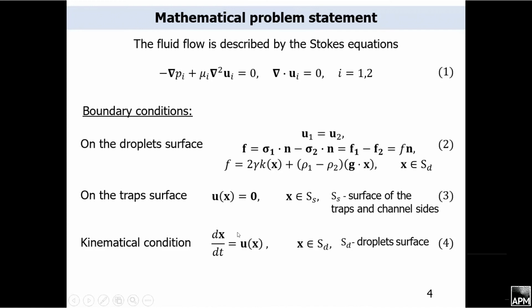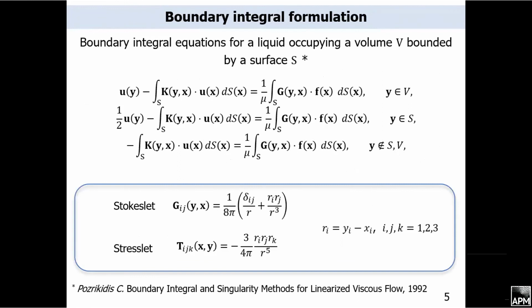We use a numerical approach based on the boundary element method. BEM is often used when solving three-dimensional problems or problems in domains with complex geometry. The main idea of the boundary element method is as follows. The original partial differential equations describing the behavior of the unknown function inside and on the boundary of the domain are transformed into integral equations that connect only the boundary values.